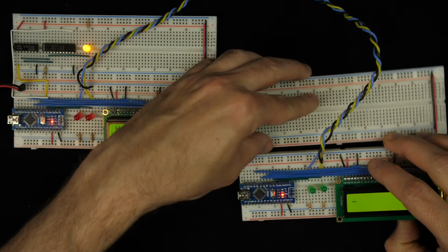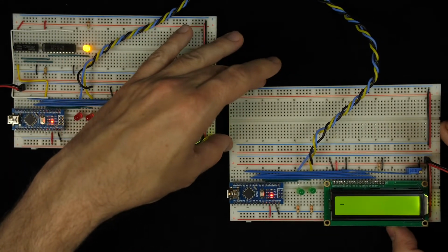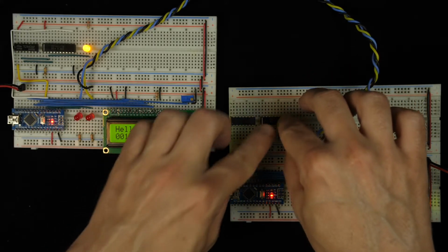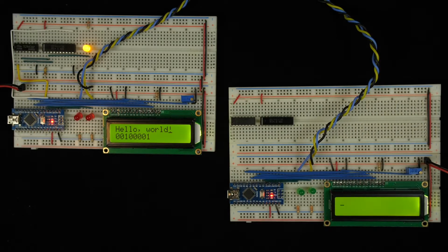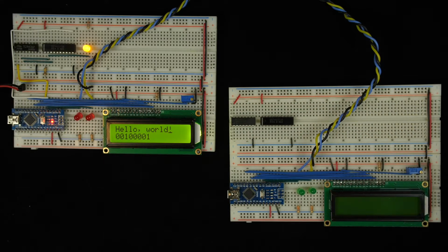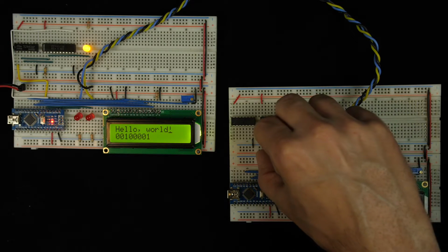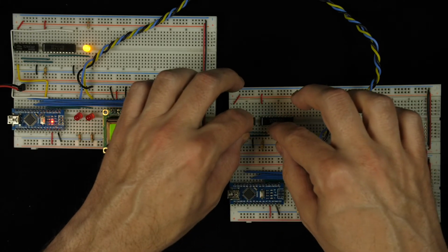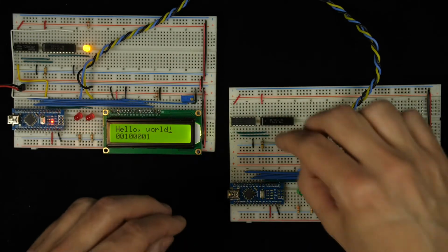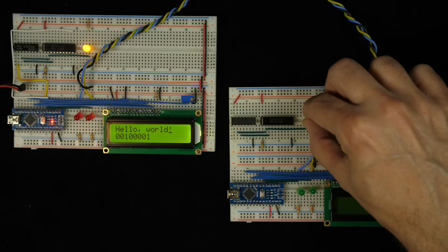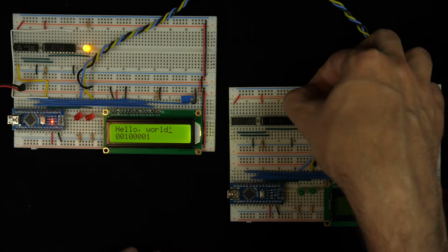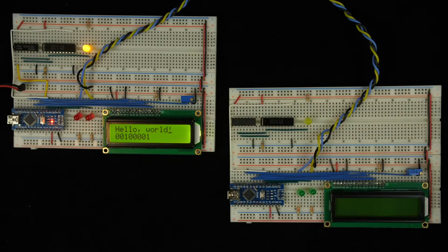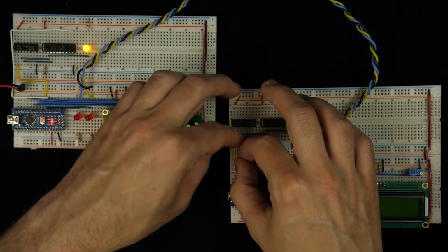So let's build the same circuit over here on the receiver side. And it's going to be identical. We've got a 74HC86 for the XOR gates and a 74HC273 for the D flip-flop. And I'll hook up power and ground to everything. And this time I won't forget to connect power between the breadboards. I'll tie the reset line high through a 100K resistor. The output of the XOR gate will go to the input of the D flip-flop. And the output of the D flip-flop will go back to one of the inputs of the XOR gate. I'll also hook the output of the D flip-flop to an LED and connect the other side of the LED to a ground through a 270 ohm resistor. Then I'll hook the received clock to the clock input of the D flip-flop and hook the received data up to the other input of the XOR gate.